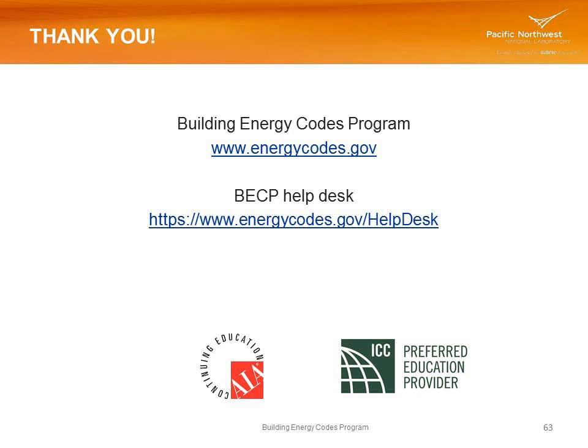is that we did talk about the supply air reset being required on VAV. Now, some people would use the primary air for humidity control and just set it at 55 degrees forever because they want the air to be that dry. Well, you only need to take it down to 55 degrees when the air is humid outside.